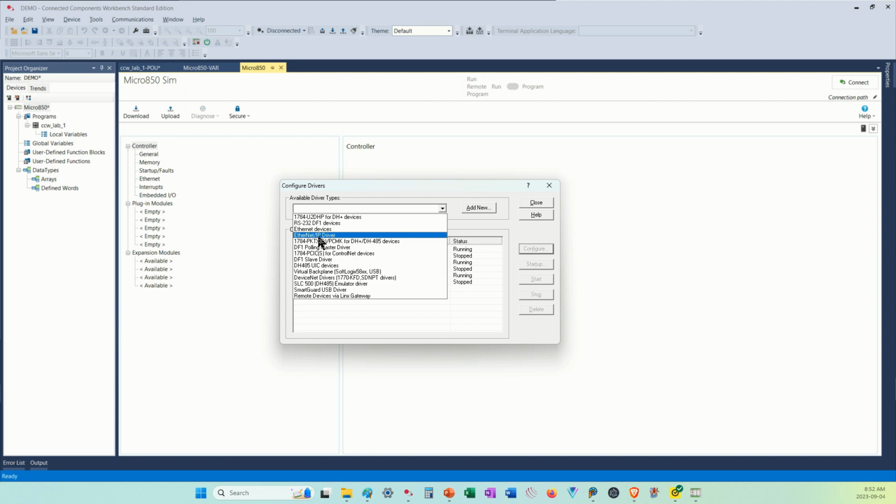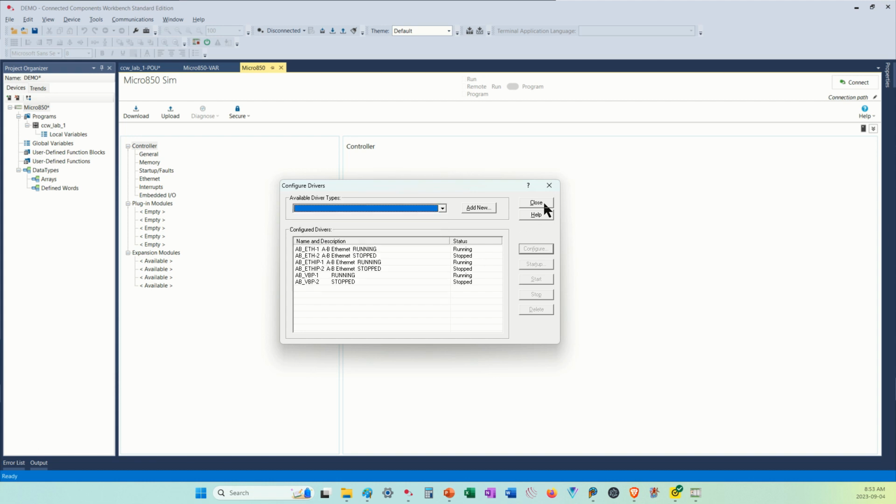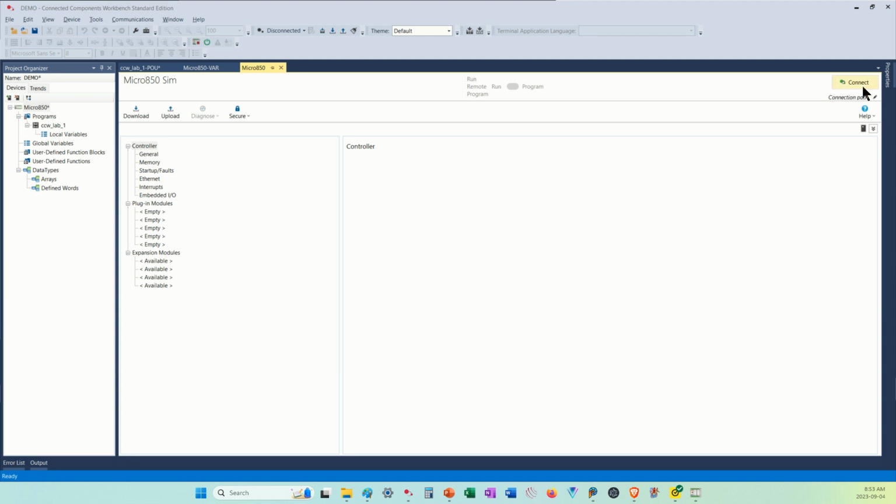to Industrial Protocol. And Industrial Protocol has higher priorities as to things like, well, if I'm going to sort my traffic controller, I think inputs and outputs are probably really important. Safety is probably important. It just sets up the priorities a little bit differently than the Internet Protocol. For other devices that do not work on the Industrial Protocol but still want to communicate, then you just use the Ethernet devices. In this case, because it's internal, either one will work. So I'm going to close this. We've already got a driver configured. Everything's good, except I don't have a path yet.